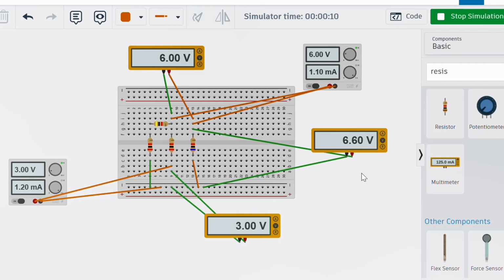Okay, so that's what you are going to do in the lab. You're going to connect your circuit, measure V Thevenin and R Thevenin. We just wanted to verify the theorem, and it's very helpful, as we mentioned, if you want to replace the whole circuit with a single source and single resistor. Of course, using the equivalent circuit will simplify the connections. For example, you can replace the whole circuit that you measured V Thevenin and R Thevenin for. You can just use one battery and one resistor.